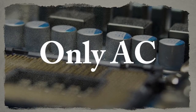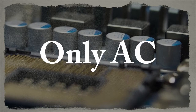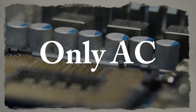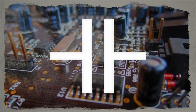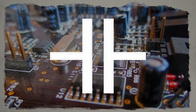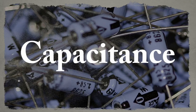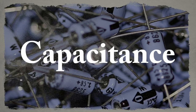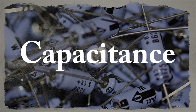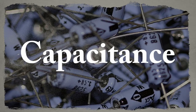A capacitor stores electric charge. It doesn't allow direct current to flow through, and it behaves as if alternating current does flow through. In its simplest form, it consists of two parallel metal plates separated by an insulator called the dielectric. The capacitance of a capacitor measures its ability to store charge and is stated in farads. The capacitance depends on the area of the plates, the separation of the plates, and the material of the dielectric.